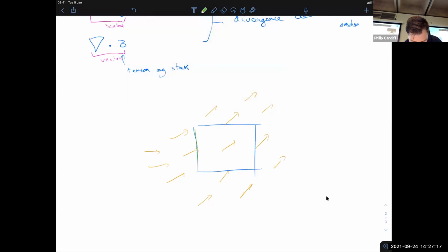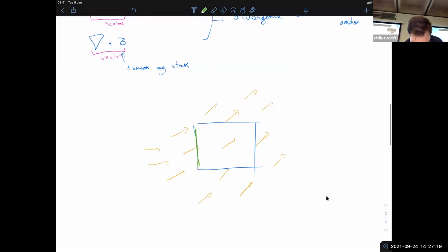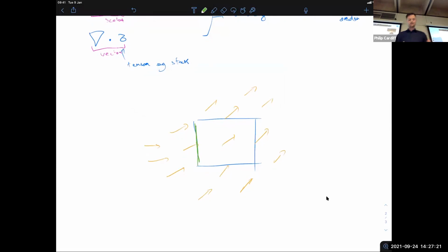if you go around each of the sides and you look at how much is flowing across that side. So the vectors will have a normal component and a tangential. So it's only this normal component that causes flow into the box at this point. And it's the same for all the sides. Some sides you might have flowing out, sometimes flowing in. So if it's at steady state, if you sum all of those up, it should equal 0.